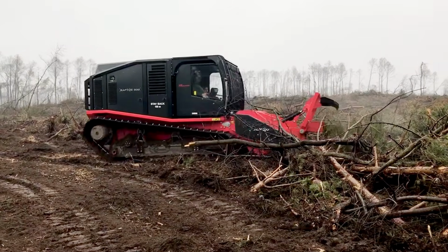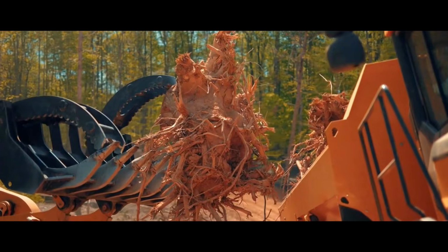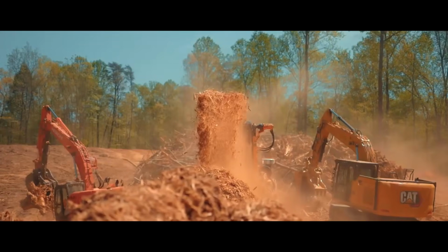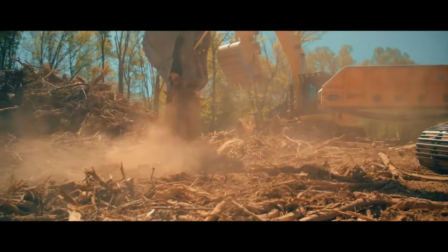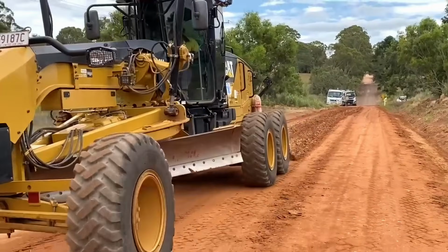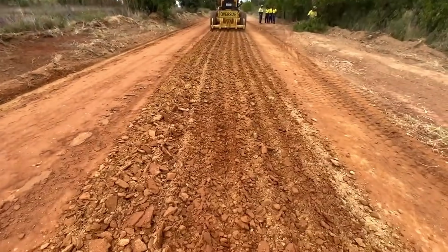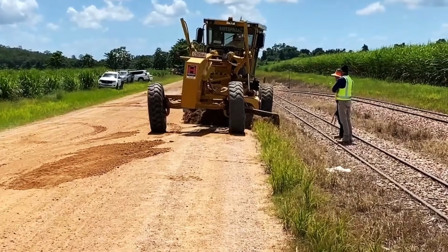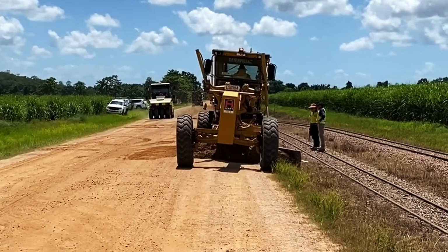The simplest form of subgrade formation is side stripping. This process involves the removal of all surface vegetation, including the root zone and any topsoil. Most projects require some degree of excavation to reach the formation level. There are two common reasons for this: to achieve the required finish levels of the pavement, and to remove bad ground, soft spots, or other unsuitable material.